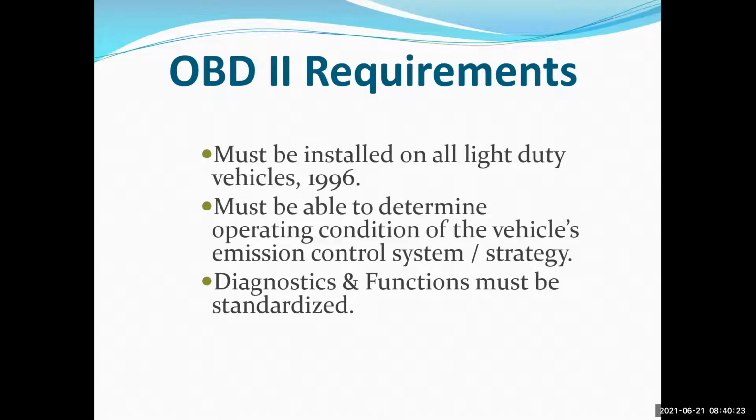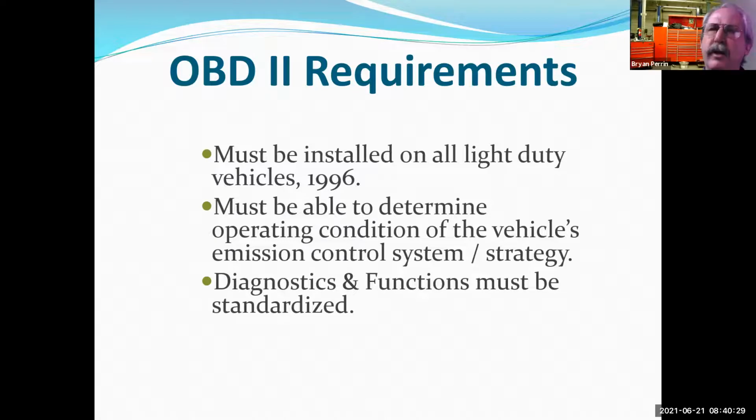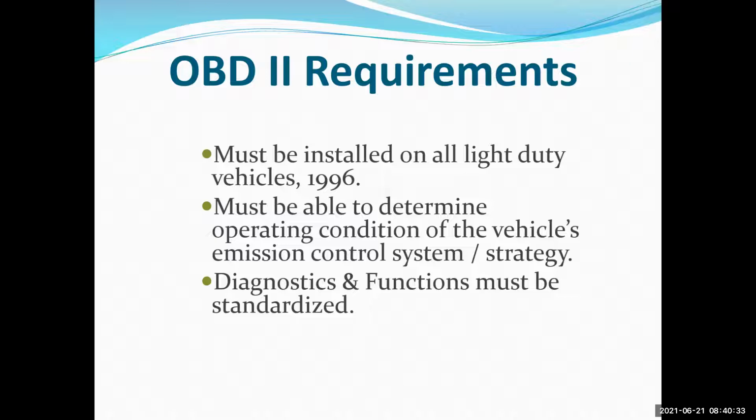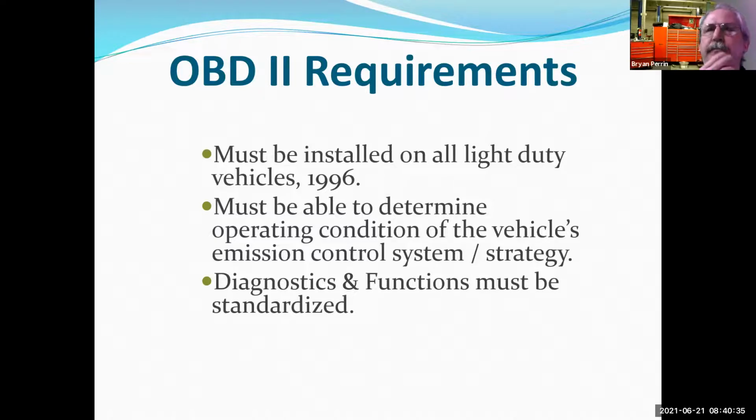All those modes coexist on the system, right? Mode 1 through Mode 9. All the modes coexist in one vehicle, correct. So most vehicles will not support all the modes. So for example, if it's new enough to have mode 0A, it can't have mode 05, because mode 05 was only used on pre-CAN vehicles and mode 0A didn't come out till 2010.